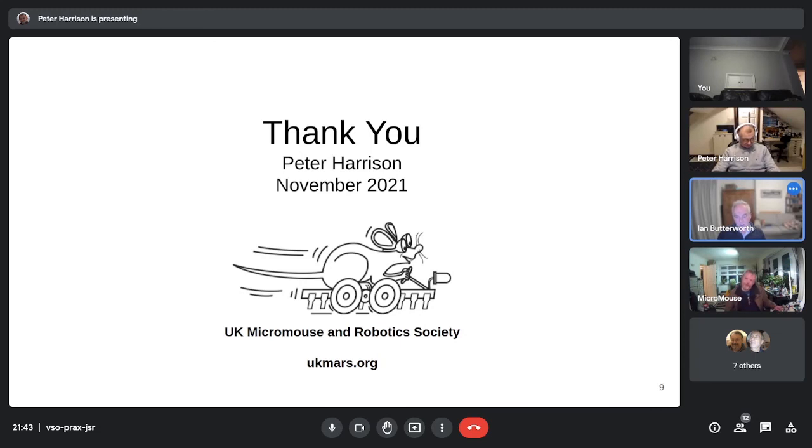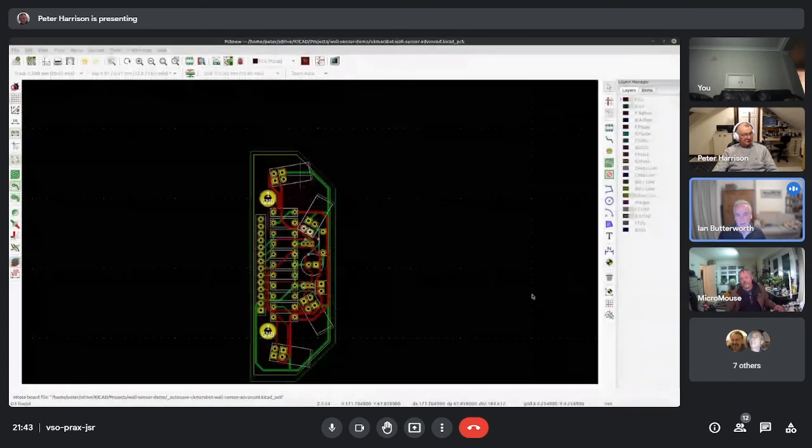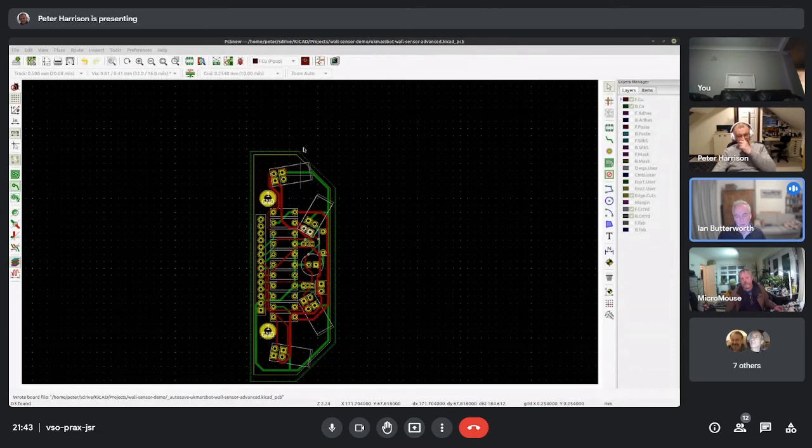It's really good. And the only thing I had trouble with was positioning some components at 45 degrees, because that's all changed around in version 5. But eventually you get there, and you can pretty well do anything you want. Once you've got your schematic drawn up properly, then when you go to the board, you can eventually rotate things around. But the keystrokes or the mouse clicks were locked into 90 degrees, and for 5.1 I couldn't find the way of changing that to a 45 degree quantum.